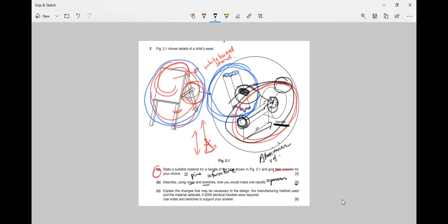I would find a drill bit that is also 10 millimeters in diameter. Yes. You drill a hole into the larger peg. Yes. And then? And then I would use a carpenter's hammer to knock the peg into the other peg. Excellent. Very good. Do you think the fit would be tight enough for the peg to not slide out, or would you need to add some contact adhesive, some wood glue?